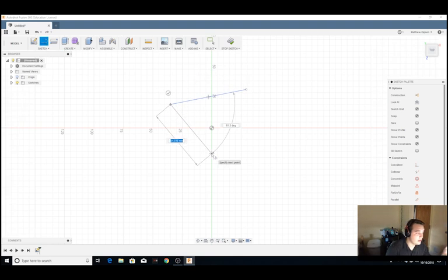The way you draw a line is point to point. Essentially, you just click and drag and move your mouse around and it'll automatically give you the degrees and distance for wherever your point is, based off what dimensions you give your Fusion workspace. Something important to note is that there are a couple snap functions depending on what you have your constraints set to, and we'll go over those more in detail later. If you're trying to draw an enclosed shape, you don't have to click directly on this point. It'd be very hard to do because points have no dimensions, but you can hover once you get close enough, see how it snaps there, and you can do that. So just a quick tip there. You can just click and drag and make your polygon and that all works out great.